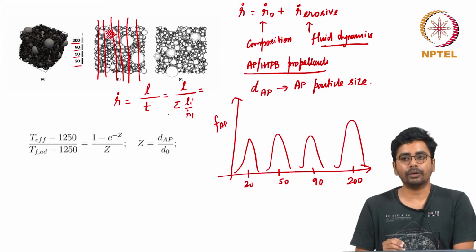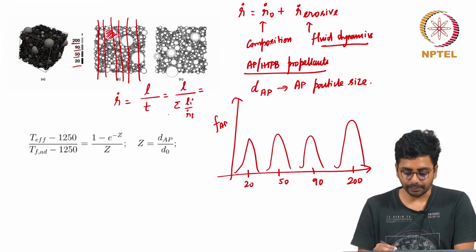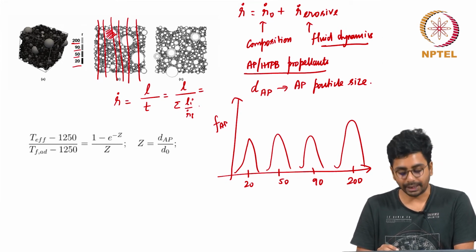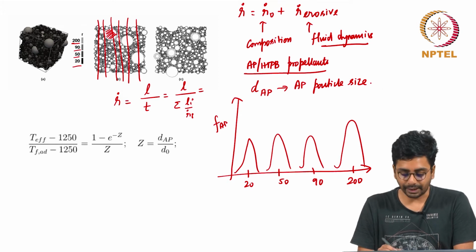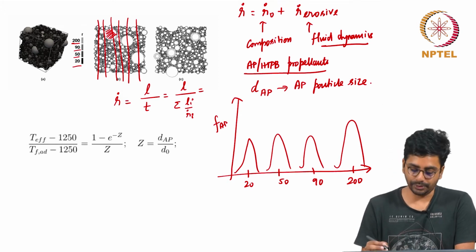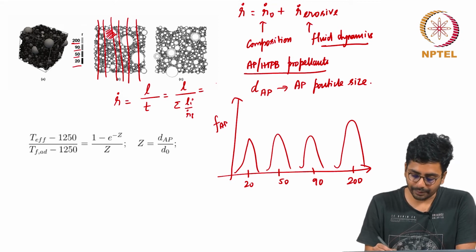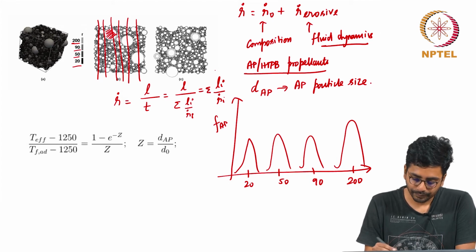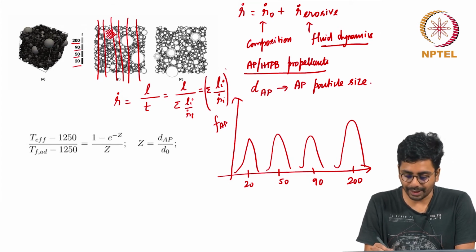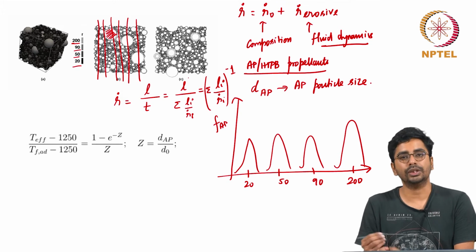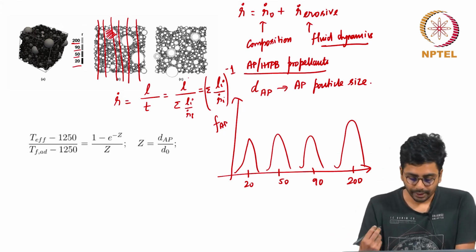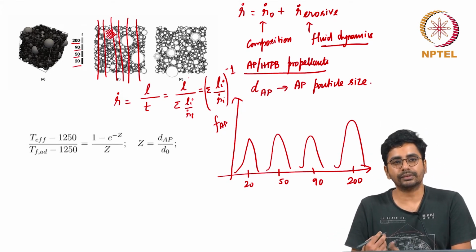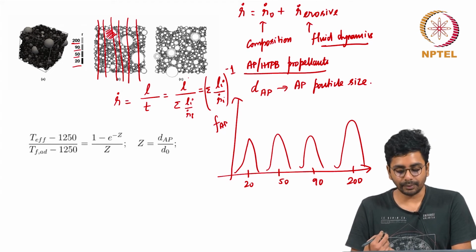So, the time for the average line to burn is the sum of the times for individual particles, which is the length of the individual particle divided by the burn rate of the individual particle, and therefore the burn rate of the propellant is the inverse of the sum of Li over R dot i. We can arbitrarily take L to be unit length. So, this is the simple idea that is used to calculate the burn rate of a propellant containing different AP particle sizes.